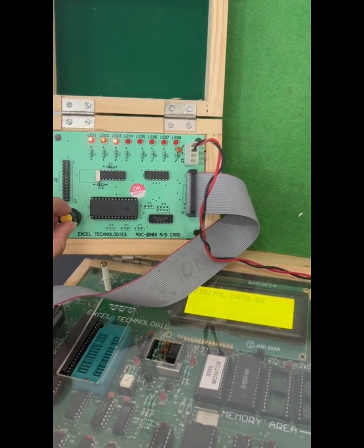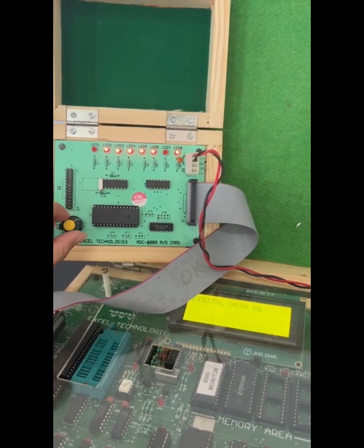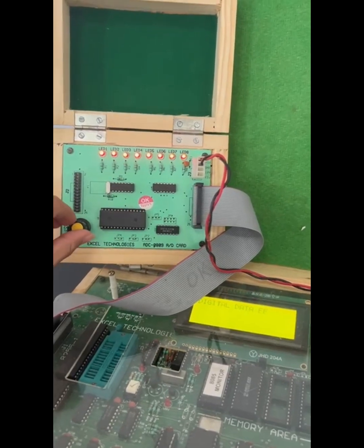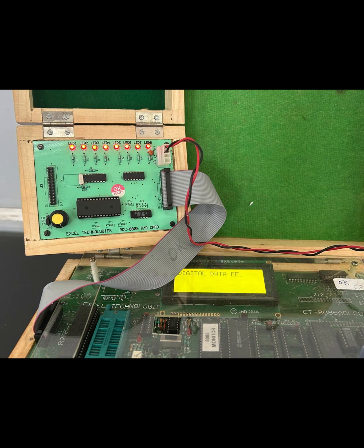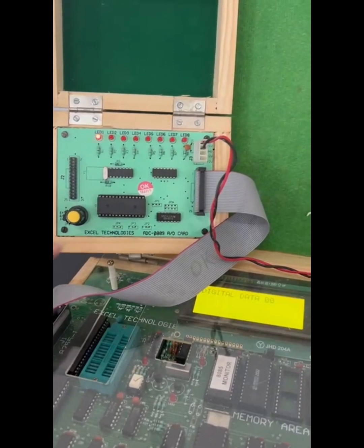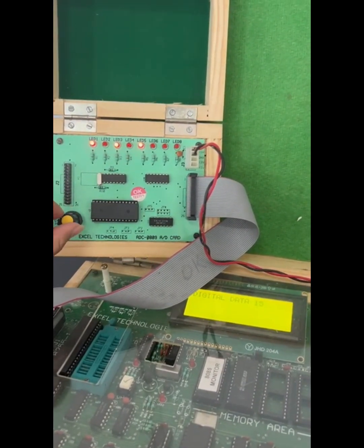To conclude, this experiment demonstrates how an analog signal can be converted into a digital value using an ADC and read via microprocessor. We observed that minimum voltage produces digital value 00, maximum voltage produces FF, and intermediate voltage produces proportional digital output represented in binary through LEDs.